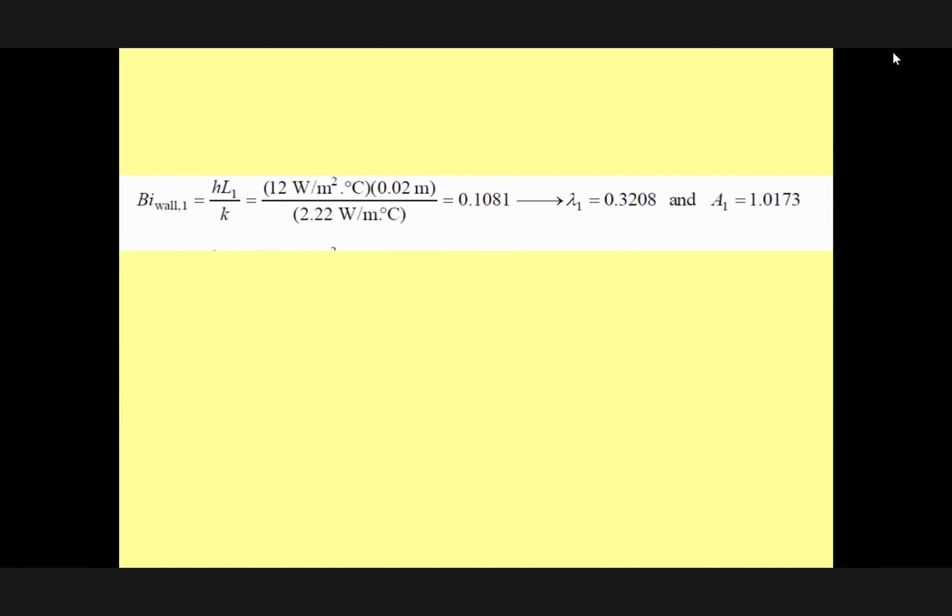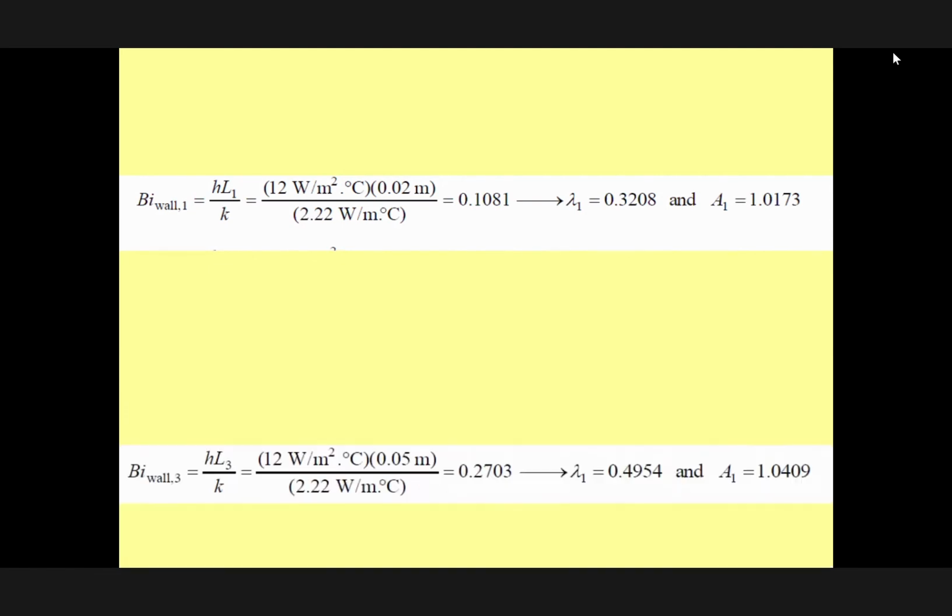Therefore, there is conduction from minus 20 to that surface, so there is a lot of conduction coming to the center. But if you look at the corner, rather than the center, there's more energy exchange to the environment than any place on the surface. Right, I understand. Thanks. Okay. Therefore, we assume that case.